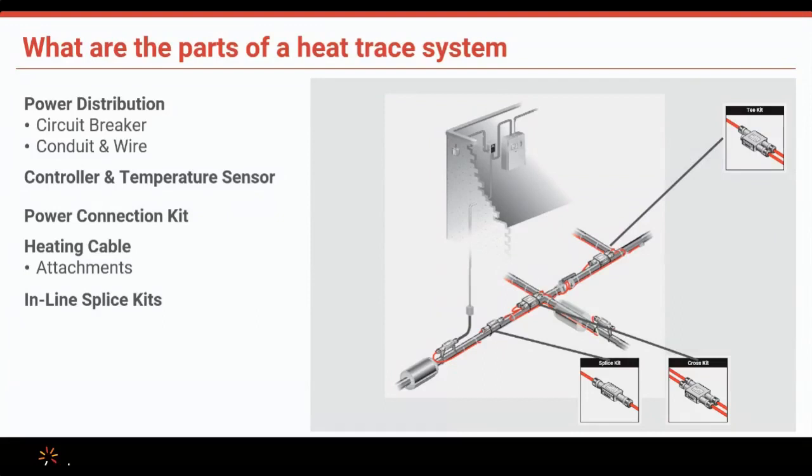In some cases, T connections aren't the right option. If you're looking at a diagram that shows a long pipe, and then a short 5-foot T segment, and this is just a freeze protection application, instead of putting an expensive T connection there, my design preference is to just double the amount of heat trace cable that goes along that T, come back to your main, and then continue on the pipe.